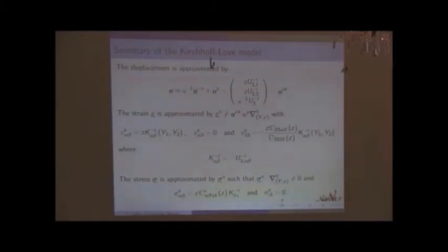But those effects depend on the square of the slenderness. I mean, the shear deflection. You have the bending deflection, which is determined by Kirchhoff's plate theory. And if you want to capture shear effects, in this situation for a sandwich panel, those effects decrease very fast with the slenderness of the plate. So it's not always relevant to seek a thick plate theory just for capturing the shear deflection, which is very often quite small. But in some applications, it's not so small.